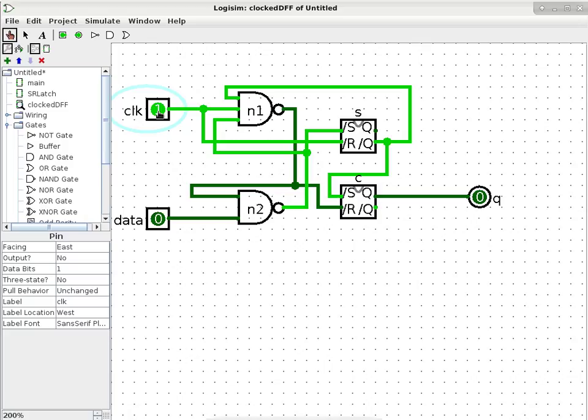Now you might think the previous circuit would do the same thing. The previous circuit, if I use the enable pin instead of the clock pin, that's exactly what's going to happen too, because when we turn the enable pin from a 0 to a 1, the device will pay attention to the D pin and change the SR latch. So from this perspective up to this point, this more complex design doesn't seem to behave any differently compared to the previous design.